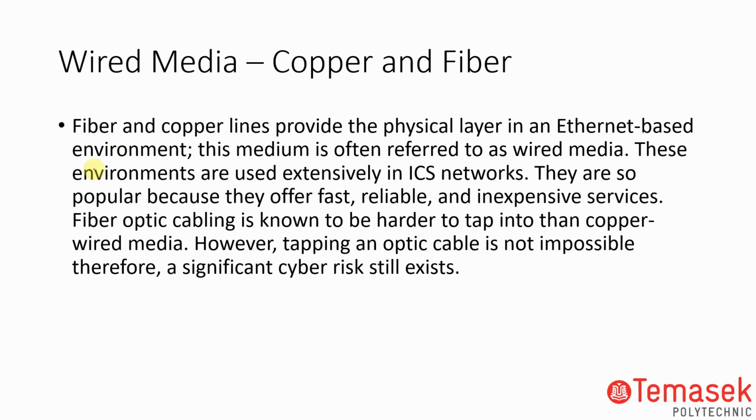So as I mentioned, Singapore has moved on to, actually the whole entire world has moved on to fiber. Okay, copper is slowly being removed. It's only at the end point that you see a copper cable. The backbone, practically I would say 80% are all fiber now, because it's a lot easier to maintain than copper. You don't have a lot of space, and it's very hard to maintain because too many cables, you don't know which is which, where is where. Of course, there is still copper cable. Just to finally tell you, there is still copper cable.